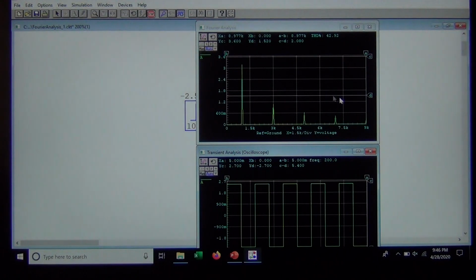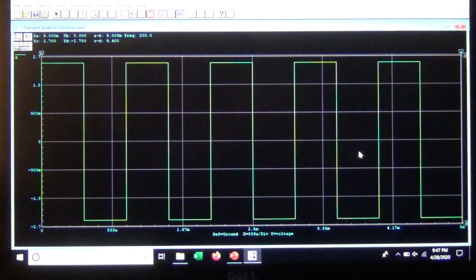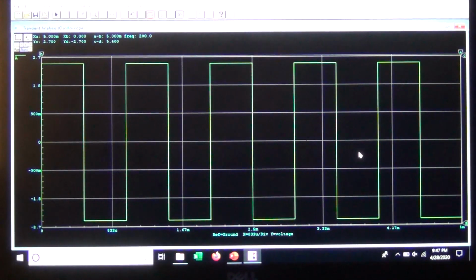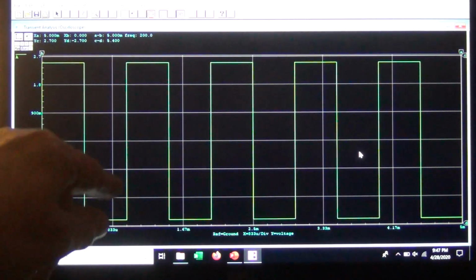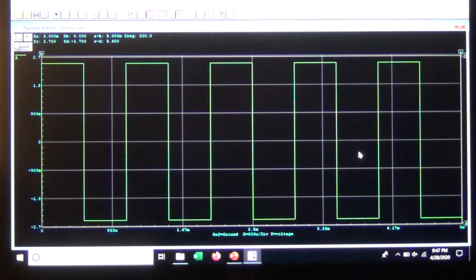And let's concentrate on the bottom one. So this is one we're more familiar with. Here we have this square wave, and you can see it goes from minus 2.5 up to plus 2.5, or 5 volts peak to peak. And I get 1000 of these per second, so we'll say its pulse repetition frequency is 1000 hertz, or its fundamental frequency is 1000 hertz. I could lay a sine wave on top of this, and the sine wave would peak here and go down to 0 and go down to minus peak and so forth. So the fundamental frequency is 1000 hertz.